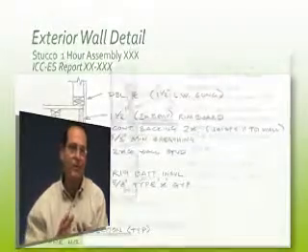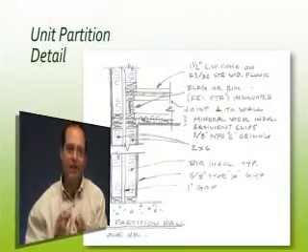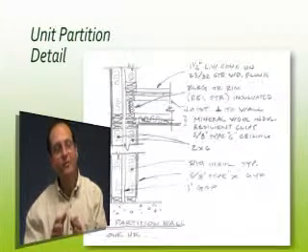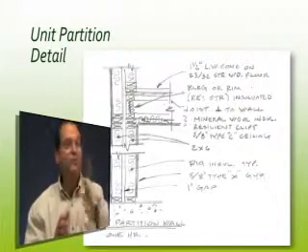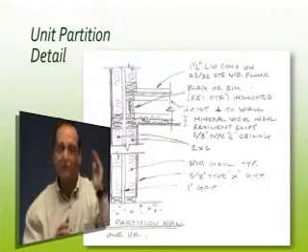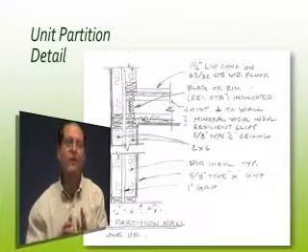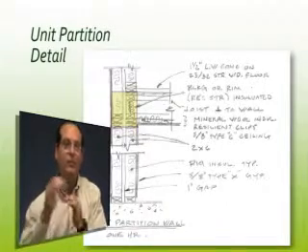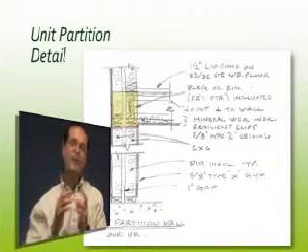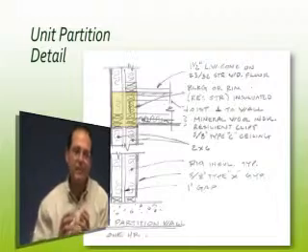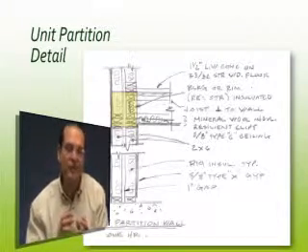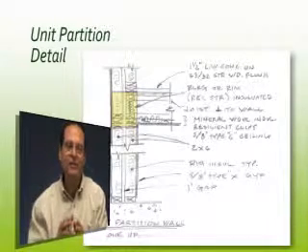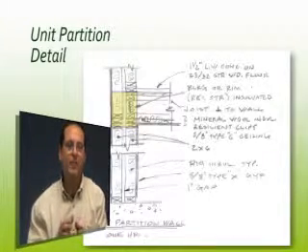The only other last piece I want to show you here is the fire wall assembly again. On the left-hand side, what you can see, this is actually a stairwell opening, so it's 2 floors high. We're just stacking walls on top of the other. No-brainer for that interior wall. The other wall that's in there, notice that the joist sets in it. So this is where things can get a little bit goofy. How you interpret this can vary. You can see the interpretation that this particular architect and building department came up with.